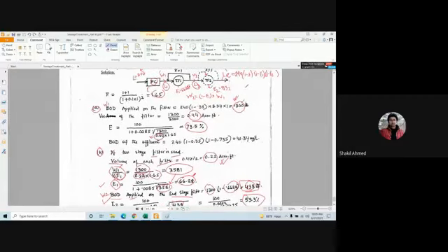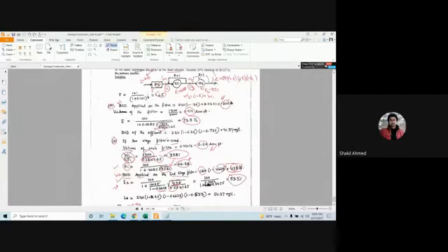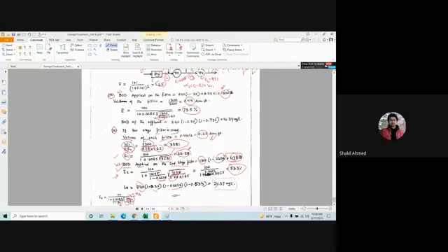So you write this 240. What is the efficiency in the primary clarifier? 35 percent, that means 0.35. What is the efficiency in trickling filter 1? E1 is 66.28, so 0.6628. What is the efficiency in trickling filter 2? E2 is 53.3, so 1 minus 0.533. Okay, so finally you get 24.57 milligram per liter.